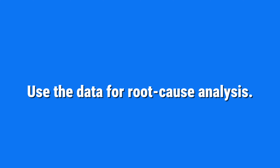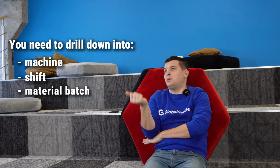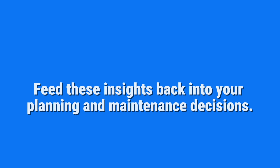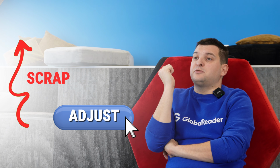Next, you need to use data for root cause analysis. Don't just look at the defect numbers. You need to drill down into the machine, shift, material batch, or interruption that caused it. That's where the real savings are. Finally, you need to feed these insights back into your planning and maintenance decisions. If one machine is drifting towards higher scrap, you can adjust workloads or reschedule preventive maintenance before costs rise.